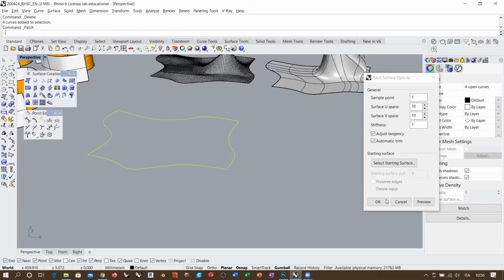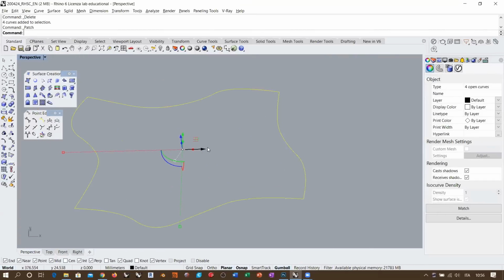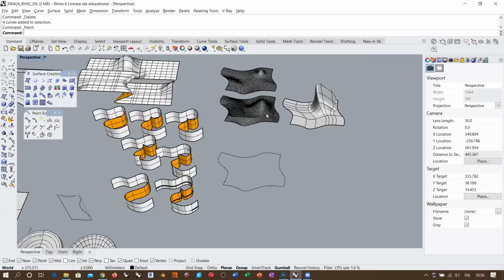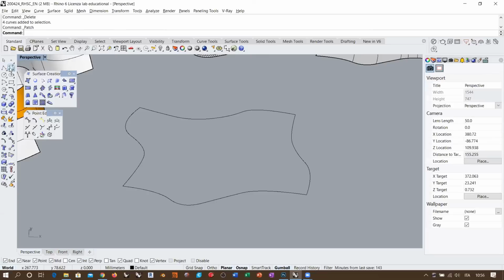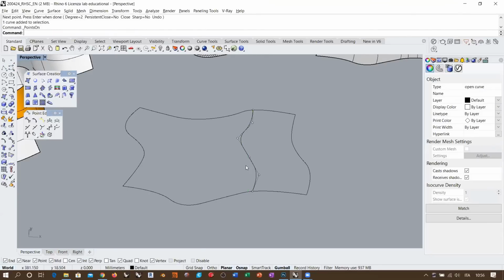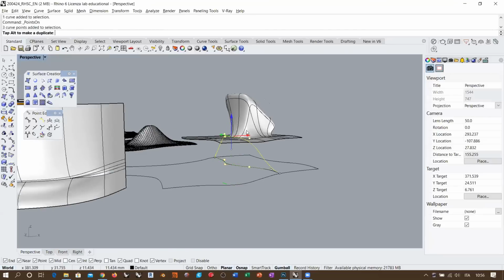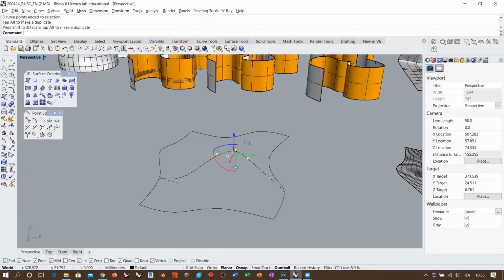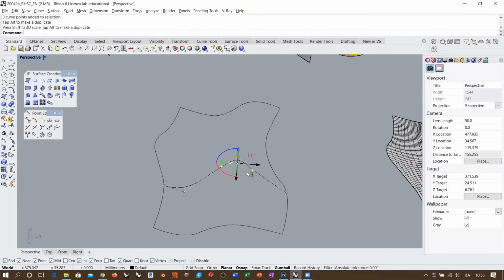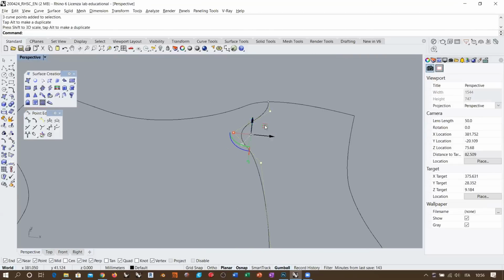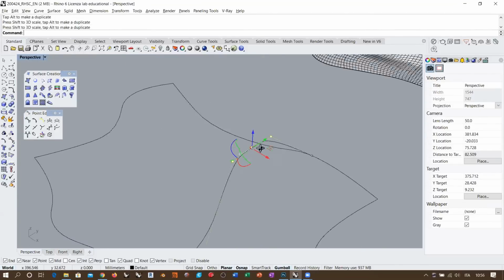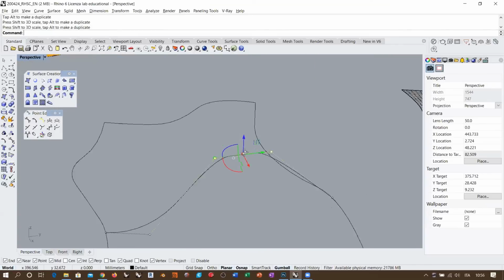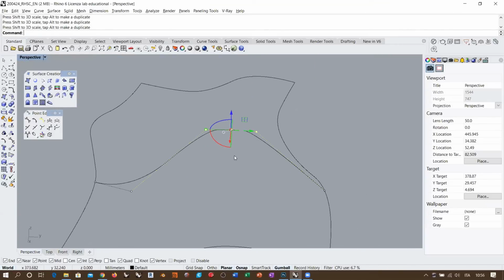Okay, so what we can do realistically with this, for example, just taking into account this situation here, right? What we can do is create an internal set of isocurves like this, take the internal points, increase their height like this, eventually scale them in order to have a more concentrated bulge area, and I'm going to scale them like this also, so I have aligned more or less these 3 points, and I have more control in this bulge.